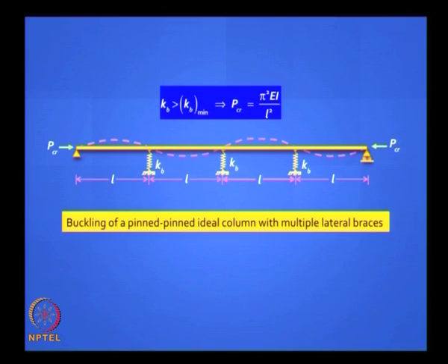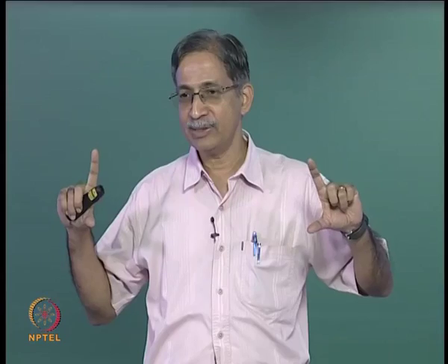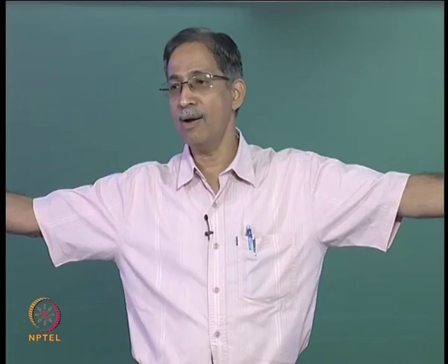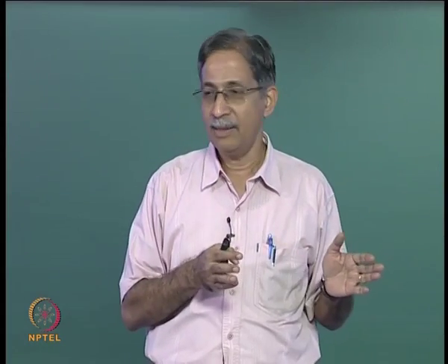For practicing engineers, these kinds of fundamentals are very important, especially when you have a very long column. You can work out the minimum bracing needed. It need not be infinite, but you have to provide appropriate stiffness to make a long column behave like a relatively short column to increase its capacity.